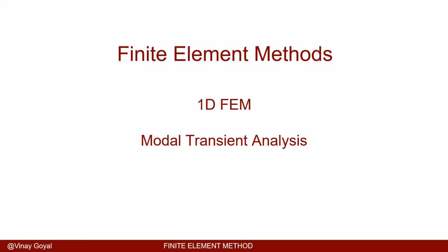Today we'll be discussing an exciting way of solving transient analyses by decoupling the mass matrix and the stiffness matrix, and coming up with an approach of just solving a bunch of masses and springs in a very simple way. This is a very exciting moment, because if you look at the transient analysis I discussed 2 lectures ago, you could see how computationally expensive it could be. Say you have a million degrees of freedom system, we have to solve that large system over time, and that can be quite computationally expensive.